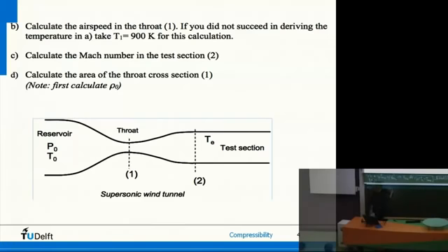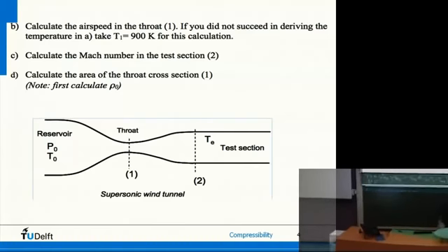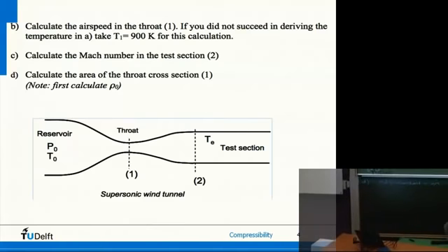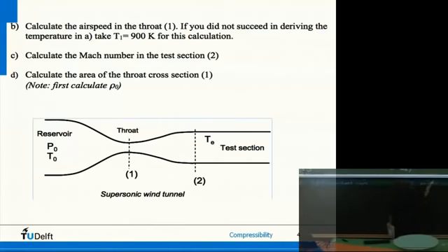So this is constant. And what is it equal to? It's equal to the mass flow. And you can check it, because if you're interested in what it is, we have rho, kilograms per meters to the third, area, meters squared, v, speed, meters per second. So what is the dimension of this? It's kilograms per second. So how many kilograms of air go through this area per second? So it's the mass flow.